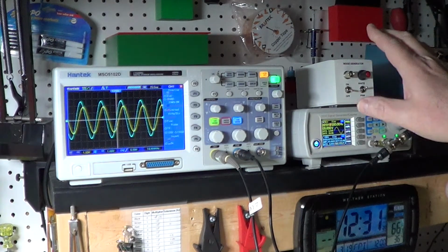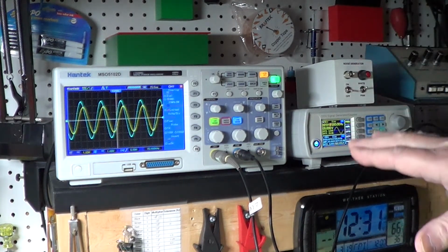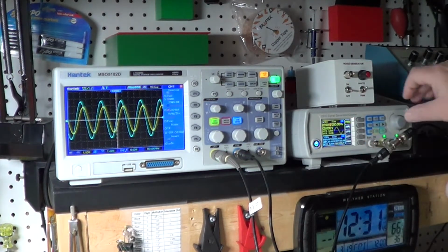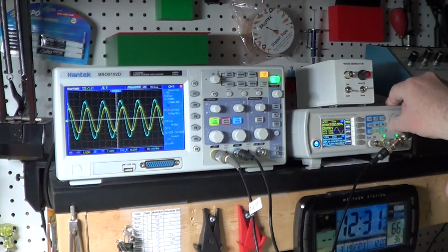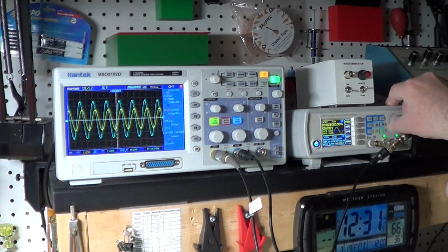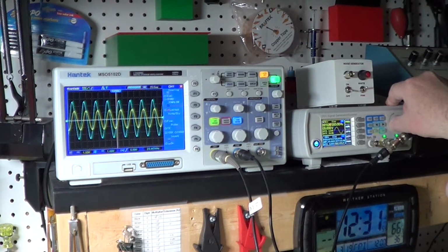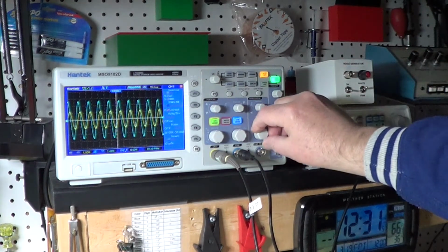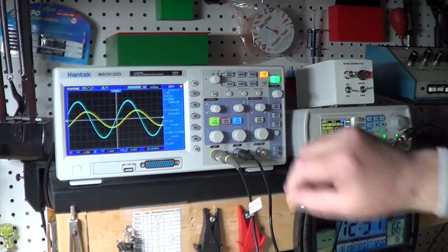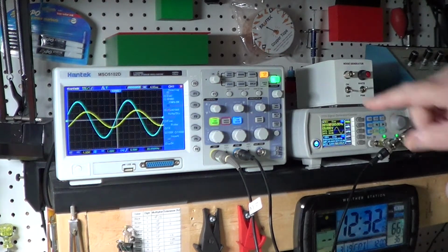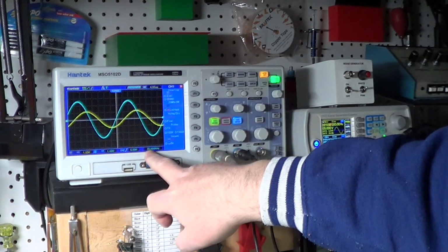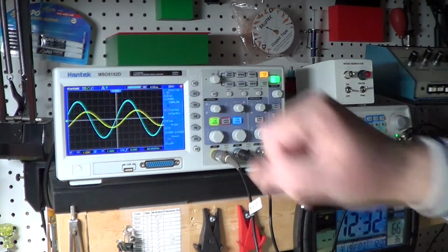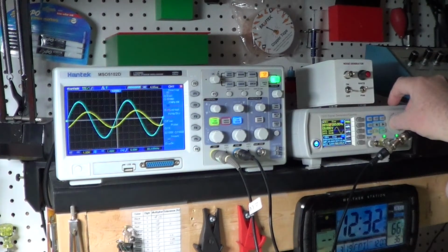This tells us that we are around the cutoff frequency of this filter, but we will talk about this more later. Let me keep going. You can see now the output is going lower, lower and lower while the frequency is increasing. Let me increase the scale here so you can see better. So for example, right now we are at 30 kHz, while the input is still at 5 volts, the output now is just about 2 volts. Let's keep going a little bit further.